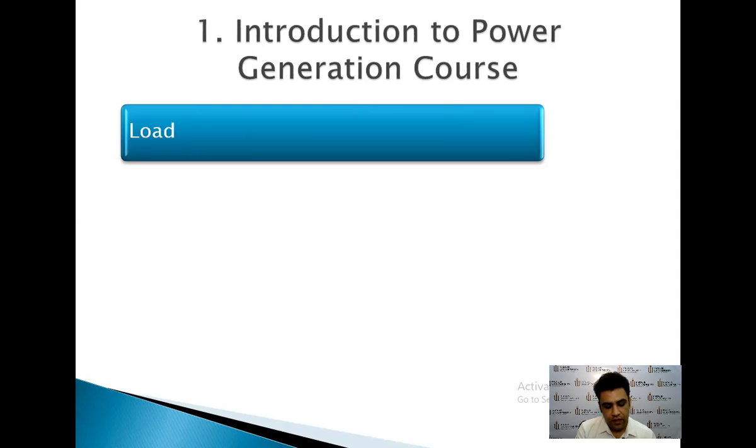To do load forecasting, we study previous data, for example, the last 5 years load, what was the maximum load and what was the load curve per month, per day. And after watching the history, we plan for future. This is load forecasting.